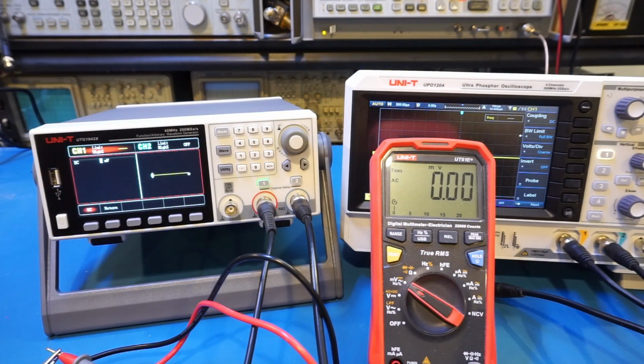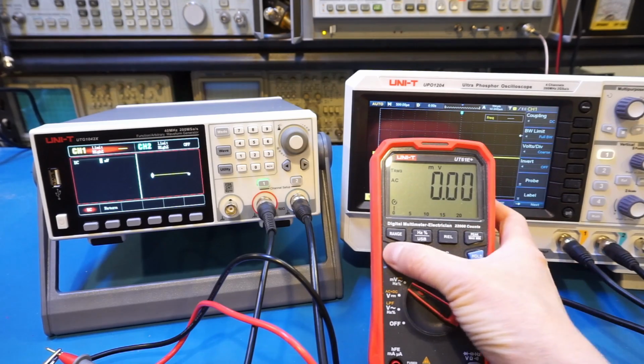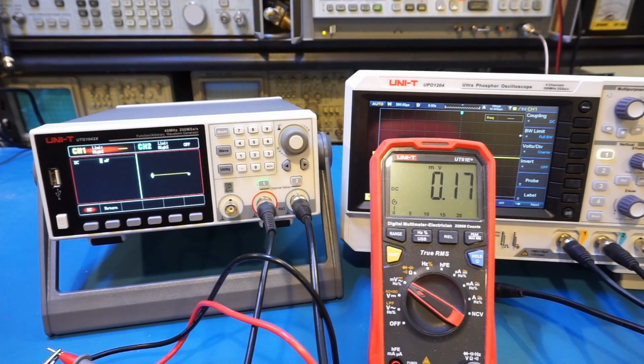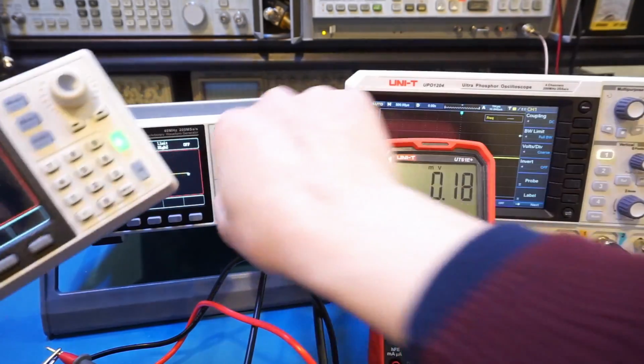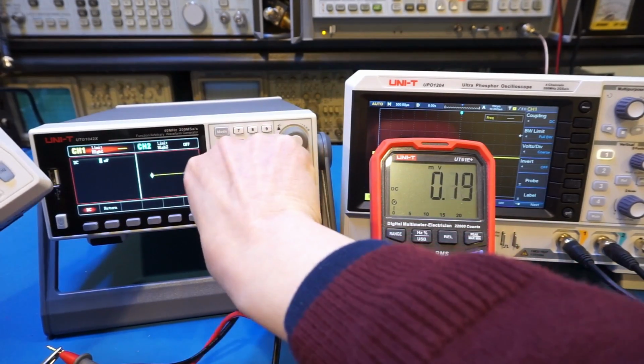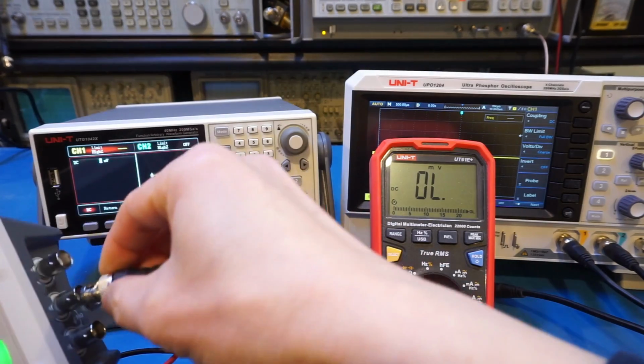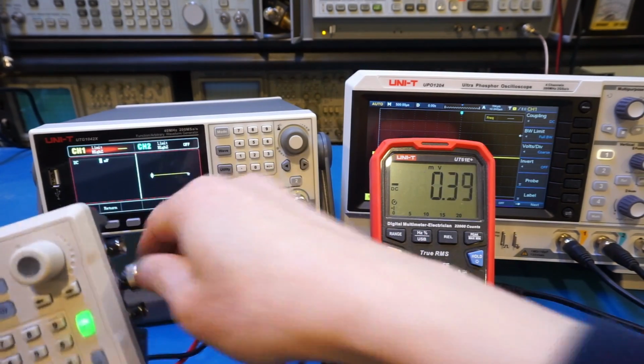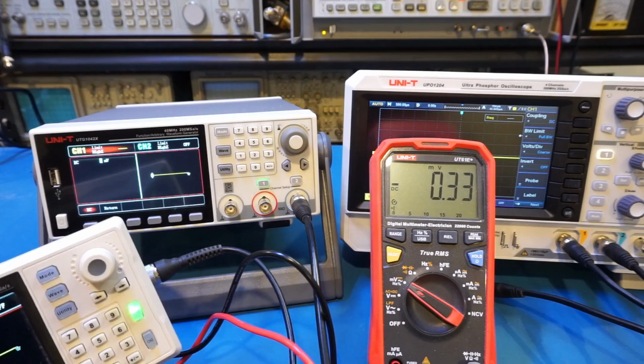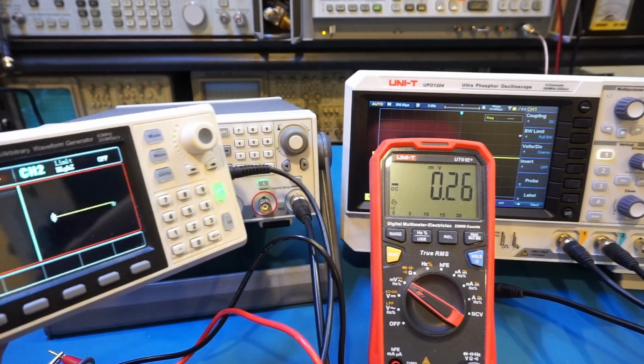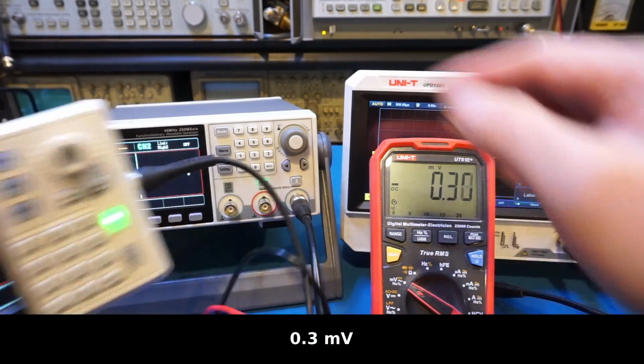So now we're outputting 0 millivolts. Actually, let's change it to DC here. That would help. So we do have a little bit of offset, which is at 0.19. And I don't remember what it was like with the UNI-T 962E. So let's actually take a look here. So now I have the 962E here. You can see that it's outputting 0 volts. So let me connect that to the 962E instead. Yeah, as you can see, the offset is actually a lot higher. Right now it's at 0.3 volts.